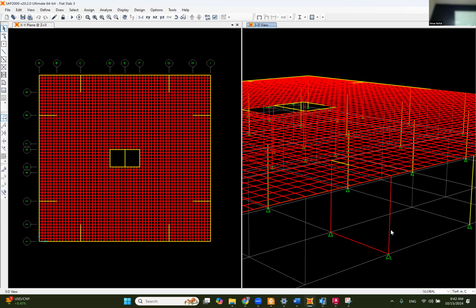So number 1, joints have to be connected. Mesh needs to be as small as 0.5 by 0.5, and definitely we need all the base conditions here to have the same condition, not only at the start and not only at the end. So let's see how we can do this. To do this, what I need to do, I need to select all the walls that I created.